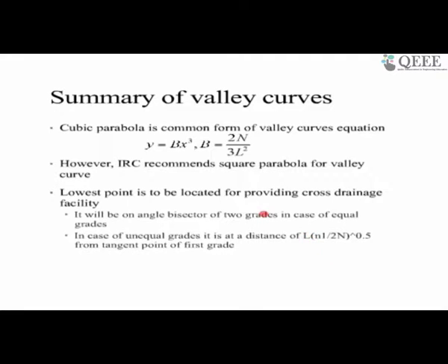If you have enough distance, the bus can come out of the main line and go to this deceleration lane, and in the deceleration lane it will slow down and come to a stop. So this is what you have to take care of, and this can be calculated based again on the stopping side distance, so your deceleration lane should be at least that long. I hope I answered that one.